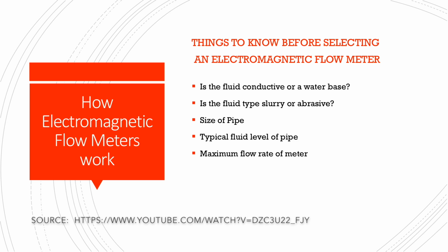There are a few things you should know before you select an electromagnetic flow meter. Is the fluid conductive or a water-based fluid? Is the fluid type slurry or abrasive? The size of the pipe, the typical fluid level of your pipe, and the maximum flow rate of the meter.